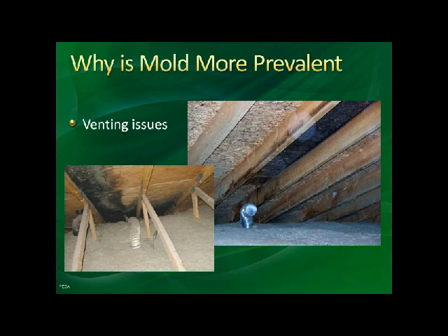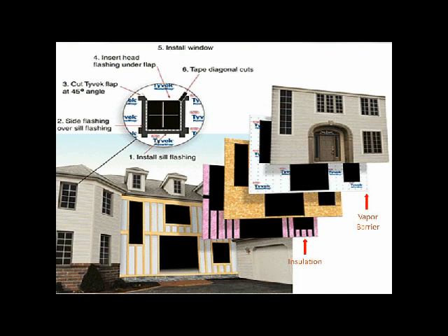As you see from a standard build of a house, as new construction is done and performed, and for those that do pre-inspections as houses are being built, they leave the particle board out to the weather elements. It gets rained on. Then they wrap Tyvek around it and seal the mold in. You have to watch for those as well.